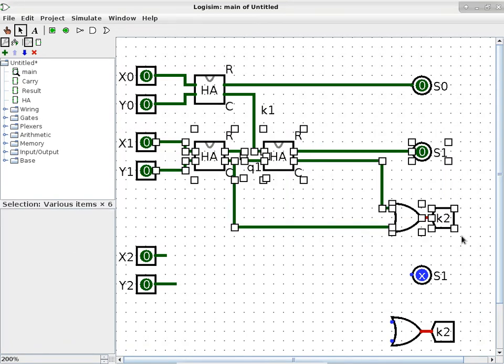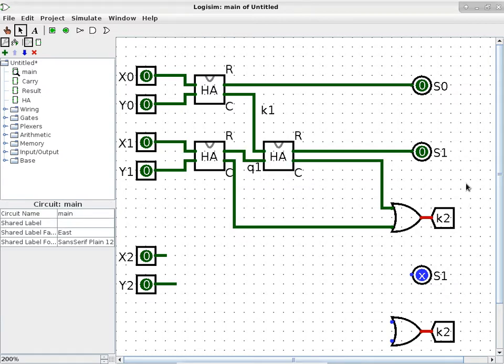Is that making any sense? The structure would be the same. Now, how do we know that structure is exactly the same, other than bit 0? Where in the notes, when we talked about this in the lecture, which part of the notes reminds you to go like, oh, this is going to be the same structure for all of the other columns? When we use the generalization of Si equals blah, blah, blah, Qi equals blah, blah, blah, they all depend only on that column, or sometimes the column before that. So that's how we know that we can create a common structure to compute all of these sums.